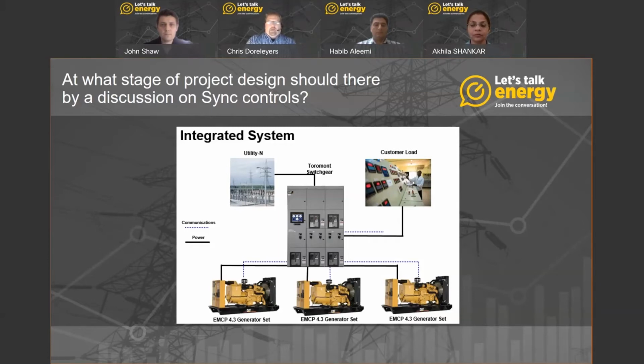So in any design with multiple systems, you want to aggregate all your generator data and balance of plant data into one area, such as a PLC. And from there, the second thing you want to make sure is that the PLC has a mechanism for delivering that data, i.e. a Modbus TCP/IP pipeline out.